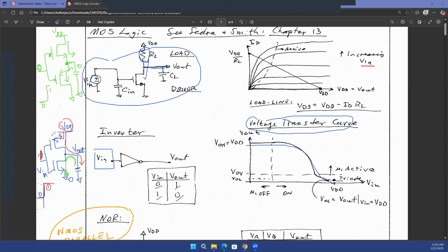And that is the reason why you always have PMOS on top and NMOS in the bottom in any digital CMOS-based circuit. You want to charge up this output capacitor, and that has to be done through a PMOS network. And you want to discharge this capacitor using an NMOS network that is generally called the pull-down network. So the network on top is called the pull-up network, and by network I mean a collection of transistors, and the network in the bottom will be called the pull-down network.